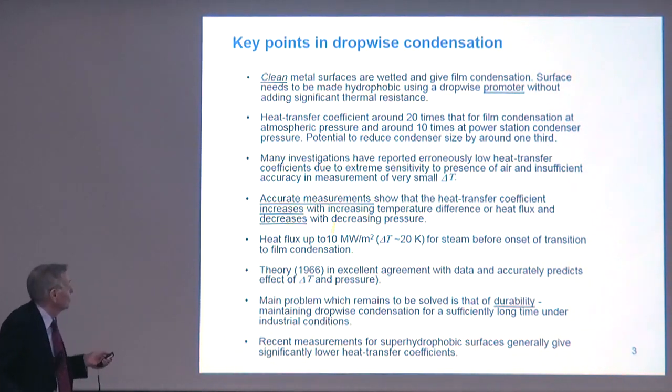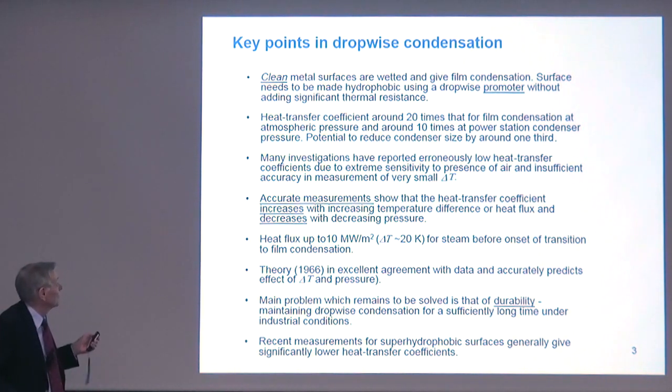Now, talking in general, before I start talking about my thesis, these are key points in dropwise condensation which I think are unquestionable. In my mind, these are absolute facts. A clean metal surface will be wetted and will not give dropwise condensation. You need to apply some kind of agent which will make a metal surface not wetted and give dropwise condensation.